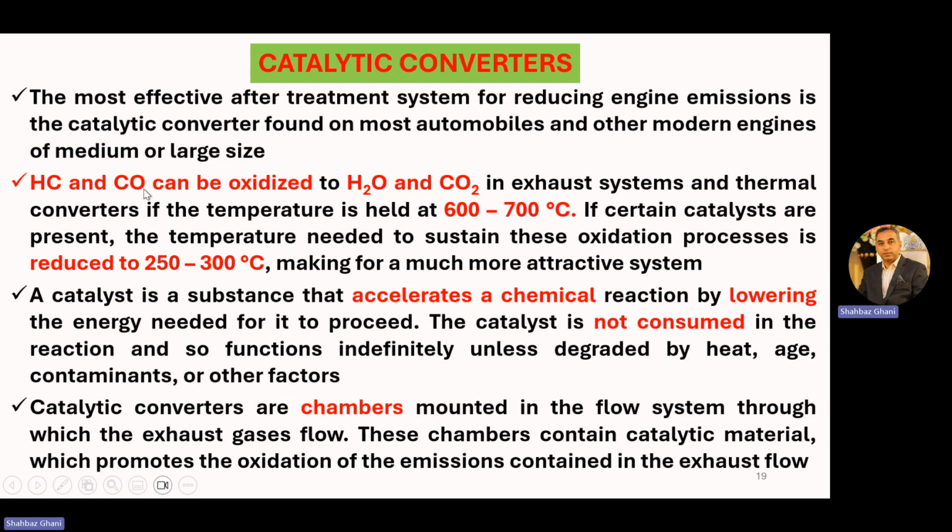Hydrocarbons and carbon monoxide can be oxidized to H2O and CO2 in the exhaust system and thermal converters if the temperature is held at 600 to 700 degrees Celsius. So we can oxidize the hydrocarbons and carbon monoxide to carbon dioxide and H2O.